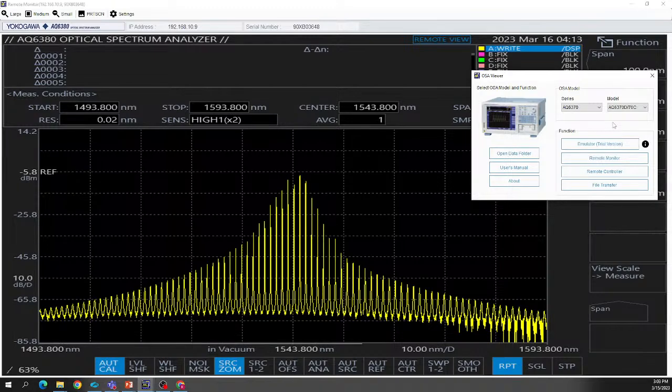But this is essentially just the reading widened so we can see more of the wavelength range. Before it was in the 1550s, give or take plus or minus 10 nanometers. Right now I've set it so that it's going plus or minus 50.